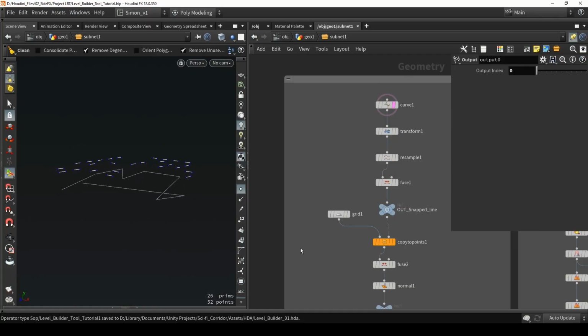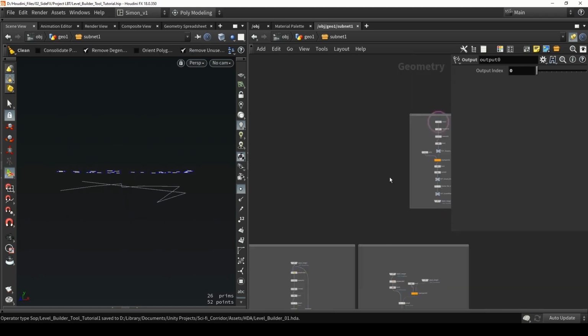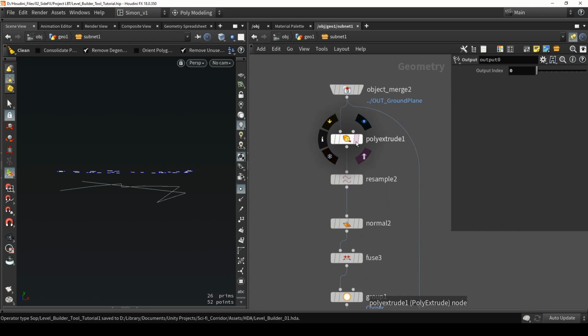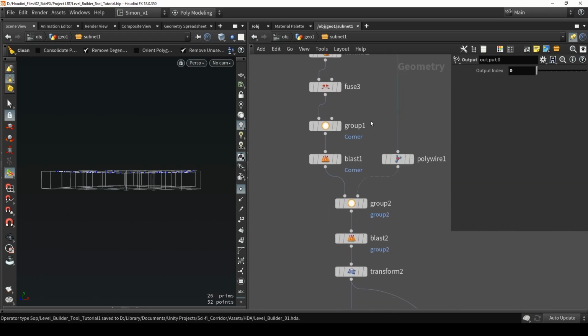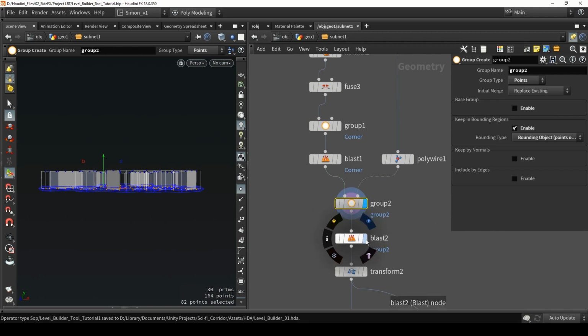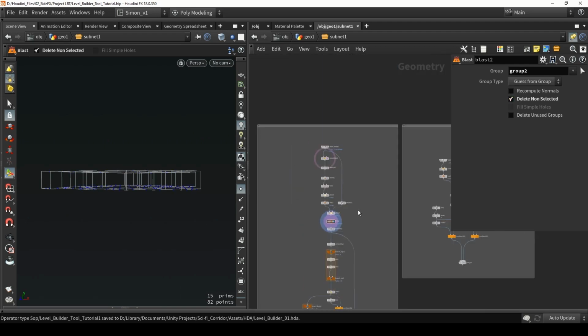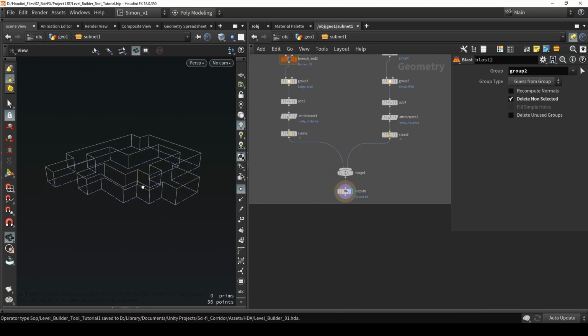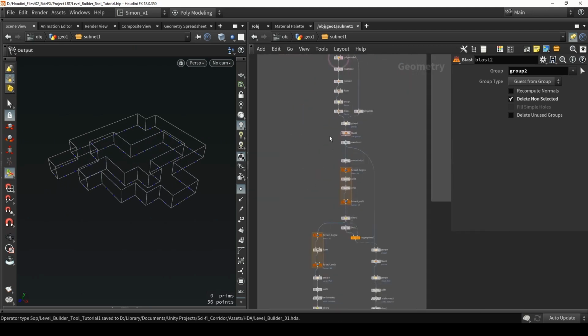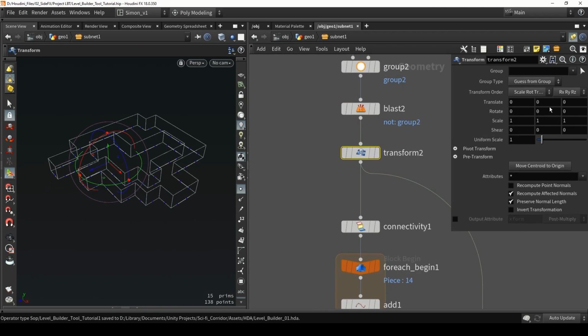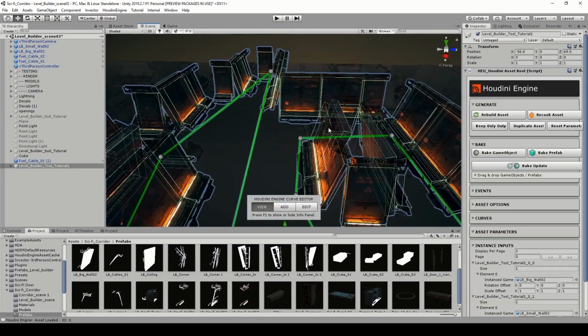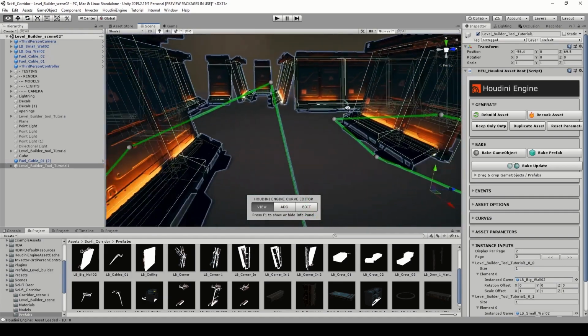And I'm going to look for the reason why my line and my points are having so much difference. And I'm guessing here that I probably over here deleted the wrong line. Yeah, I deleted the wrong line over here. I should have inverted this. And now this should be better. Also remember that I placed a transform here. So if it's not good enough still, I can still, for example, fill in the value 3 in here, or something else. So rebuilding my tool, and now it's being placed better.